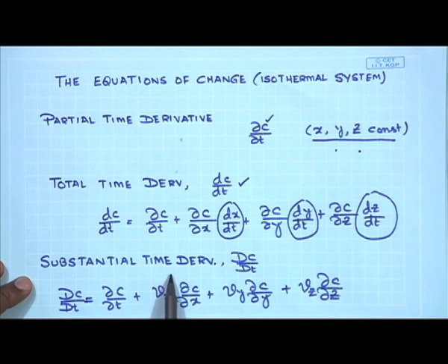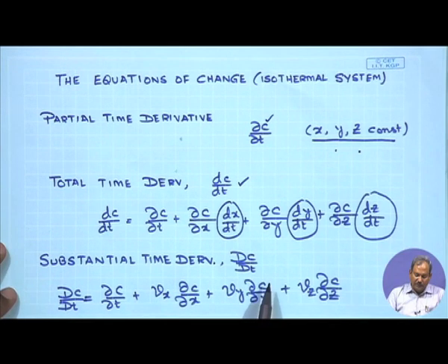So, now you do not have a velocity of your own. Whatever be the local fluid velocity, that is the velocity of the reference frame, and the number that you are counting is some sort of a derivative, dc dt, the time derivative of the number of persons, where the reference frame moves with the fluid with its average velocity. It can also be said to be a derivative following the motion. This is generally called the substantial time derivative.